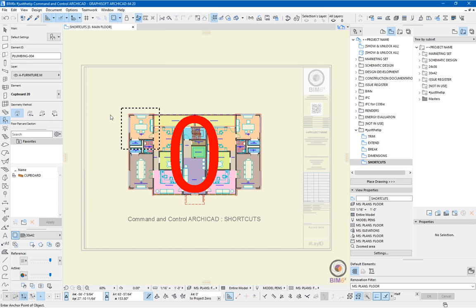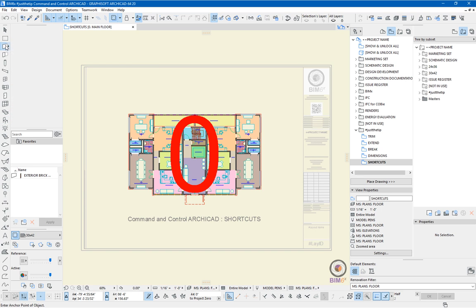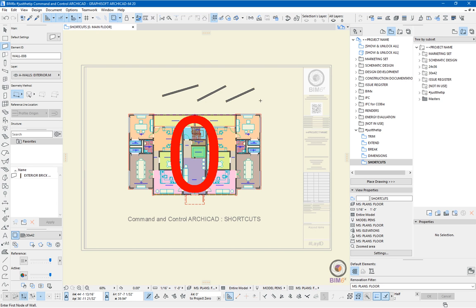The next one I've already mentioned, the undo command. If I was to draw something, and decide that once I've done it, I don't want them, I can literally just do Control Z, and that does an undo. So I did it 3 times there to take out the last 3 options. There is a limit to the number of undos. It's also cleared by hitting the save button, but generally undo is your backup plan if things go horribly wrong. Not to confuse with a backup PLN, that's a different thing, but anyways, that'll do for now.